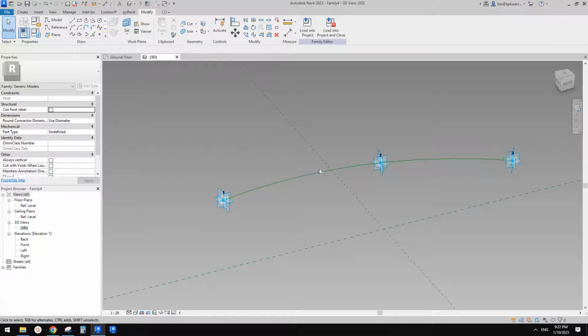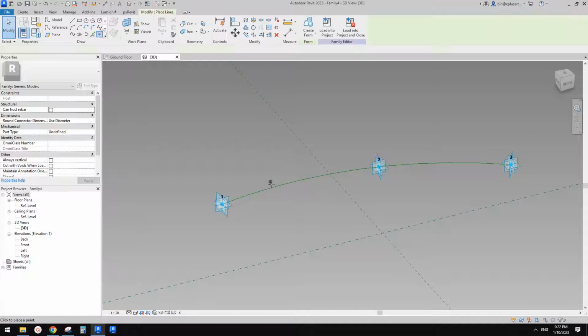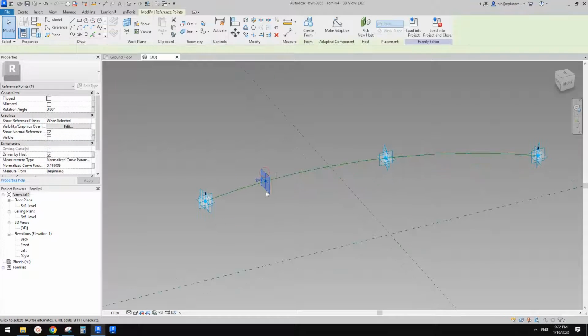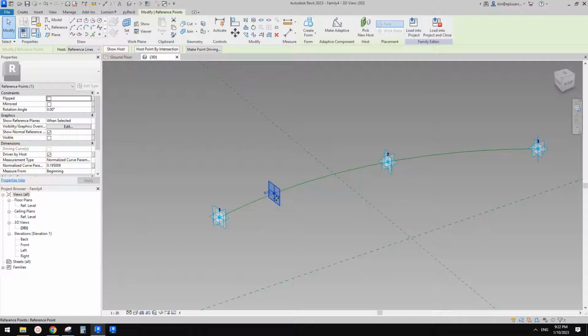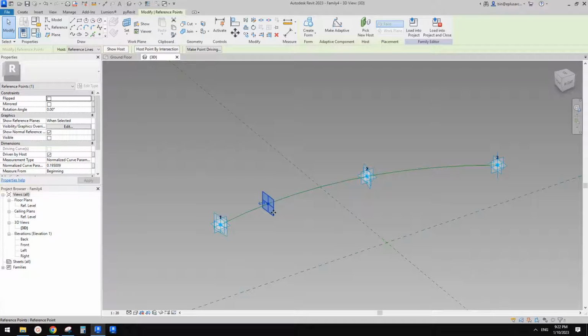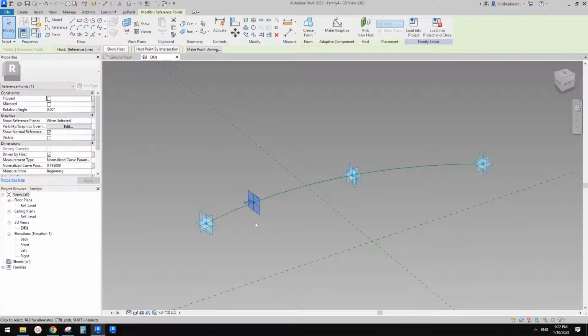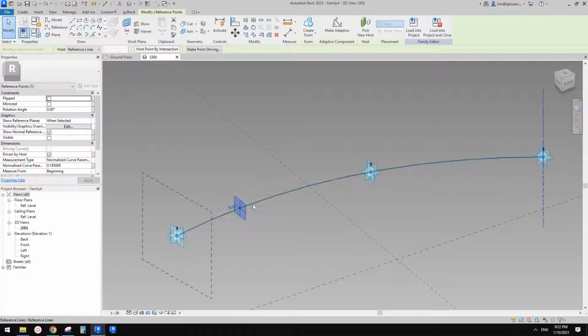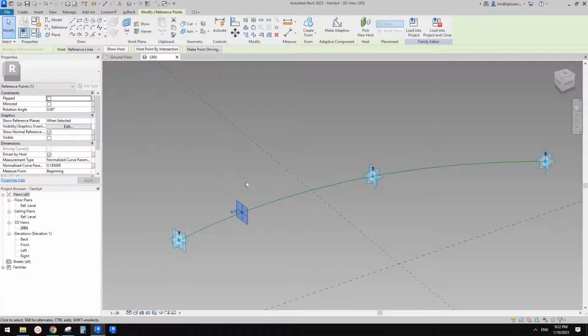For the circle, it's very simple. We need at least 2. Because we're going to make it parametric, we need 2 profiles. If you follow me, you should already know why we're using 2. Because if you use 1, it won't work. It will break. Sometimes it will break when you change the size, but sometimes it will create an irregular shape instead of a sweep. Okay, so now let's do it.